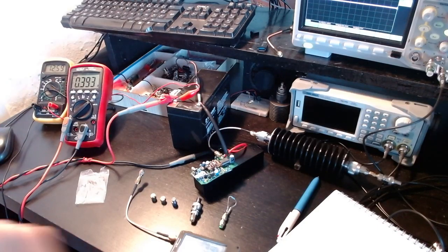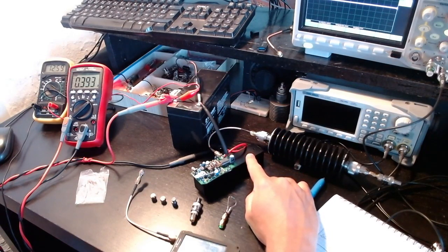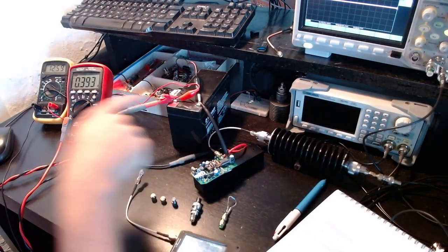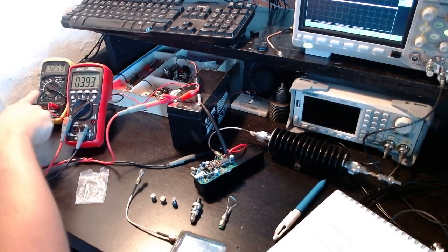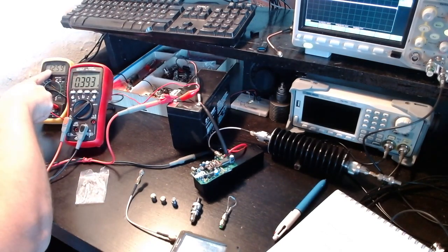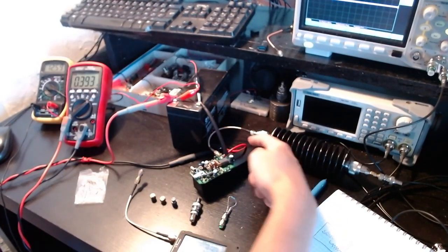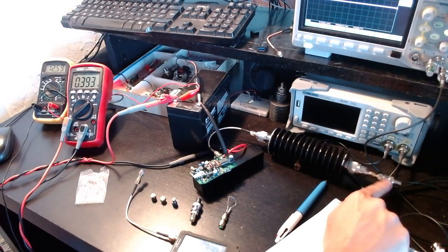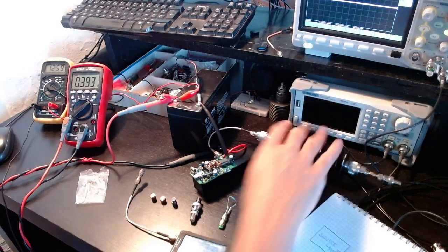So this is a continuation of my previous episode, and I'm still playing with the QRPLabs 10 watts linear amplifier that I have here. It is connected and powered up by a battery. Here you can see the amperage, so the current consumption, and here the voltage of the battery, currently at 12.6 volts. So here I have the amplifier, and the output is going to this attenuator and then is terminated by a 50 ohm load. So basically the output is completely dissipated in it by this thing here.